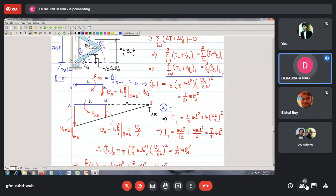So that is what I calculate, I of this member, and that is 1 by 12 mb square plus this distance, which will be b by 2 plus b, it means 3b by 2. So m into 3b by 2 whole square, and on simplification it turns out to be 7 by 3 mb square. So 7 by 3 mb square is going to be I of this member, means mass moment of inertia of this member about the instantaneous center of rotation.